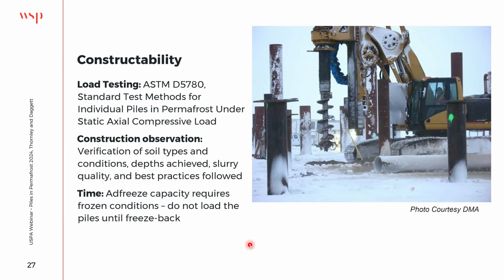That's one piece. And then time, right? Adfreeze capacity actually requires frozen conditions, obviously, but it's something that takes a little bit of time to evaluate. And so looking at how long it will take to freeze your pile back is oftentimes part of the design process to let the contractor know when they can actually start building the structure on top of the piles, because that is an important piece of the process of gaining that capacity for those piles.